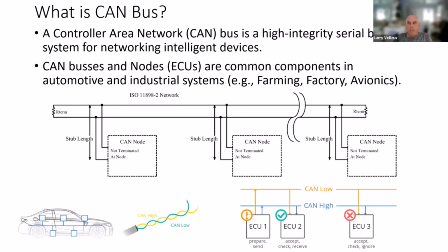All right, so CAN bus: controller area network, bus topology. It's a serial bus, meaning only one bit can be on the wire at a time. It's actually implemented with two wires, the bus itself, and then the nodes, which in the automotive world are typically referred to as ECUs, electronic control units, connect to each of those buses. They could physically be spliced in. In some implementations, they might just couple an inductive device on there to pull the signal off of the wire without actually cutting into it. But there also is a way to have a hub where everybody connects.